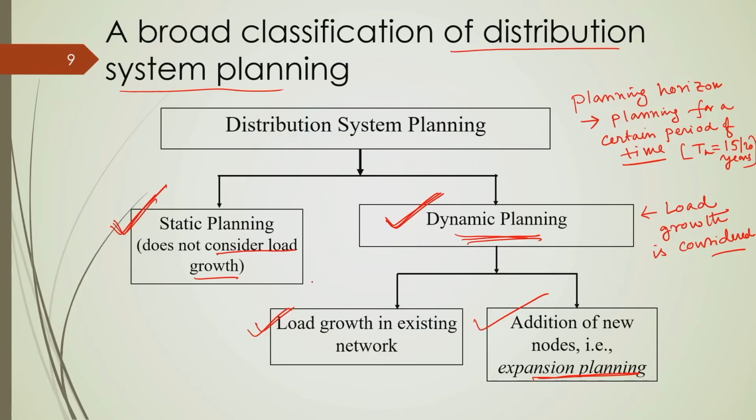In those cases we do not need to install any additional distribution feeder or distribution line, as long as the capacities of all the components of the distribution network can handle the new loading. Okay. But this is one case.